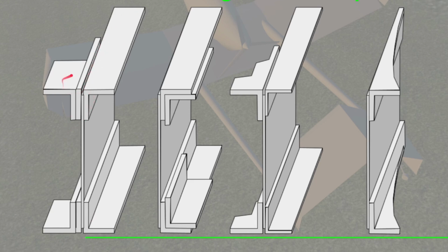So for example, here where we want it beefiest, we've got a couple of angles here. We've got a bar here. And you can see this front angle is only going a little ways out. This bar is going a little bit farther. And then this back angle is going all the way. So we've actually increased the strength of the spar cap in 3 areas, in 3 steps.